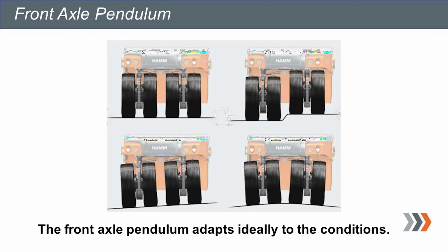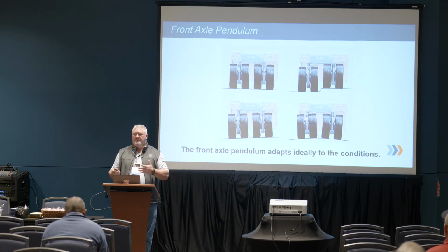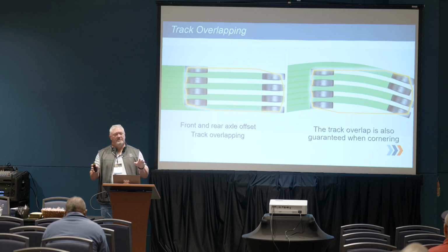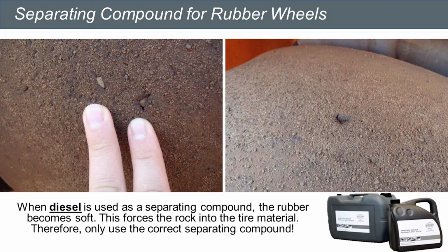Rubber tires are nice because they balance how they compact on uneven surfaces, especially on soils. But anything, especially like joints and stuff like that, we can get a lot of even pressure and even compaction effort with the tires on a rubber tire. All manufacturers have rubber tire rollers that have offsets front and rear, so you get the kneading effect in between the tires, and you also get the kneading effect front and back.